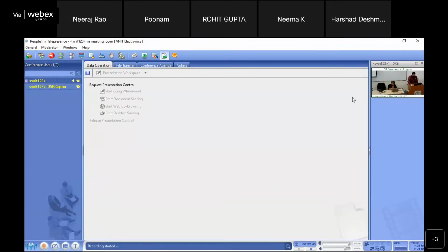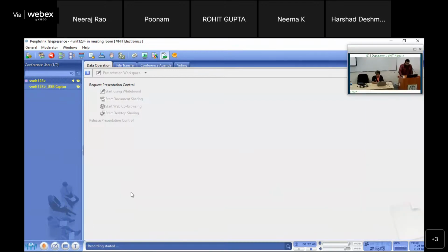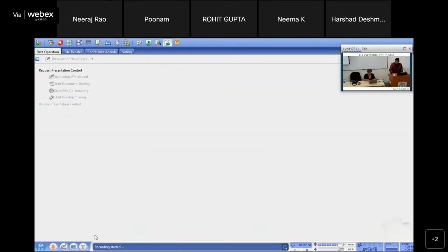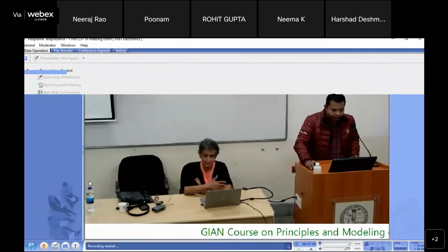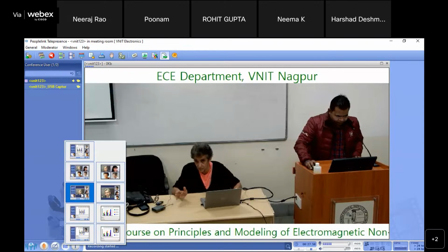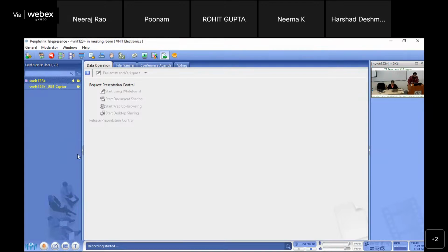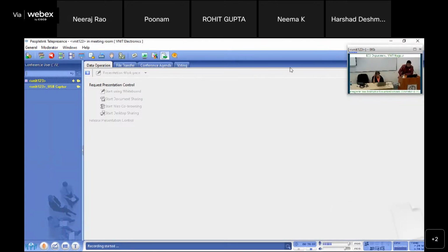Yeah. No, diffusion, you're always trying to calculate the unknown U, okay? But the governing equation varies in space and time in this manner. That comes out of Maxwell's equations. If I don't look at the steady state case, for a pulsed eddy current, I really have a diffusion equation. That's what happens.